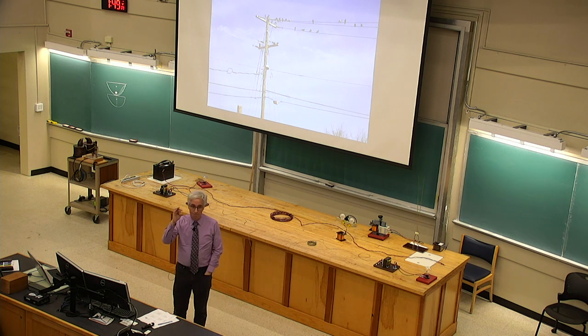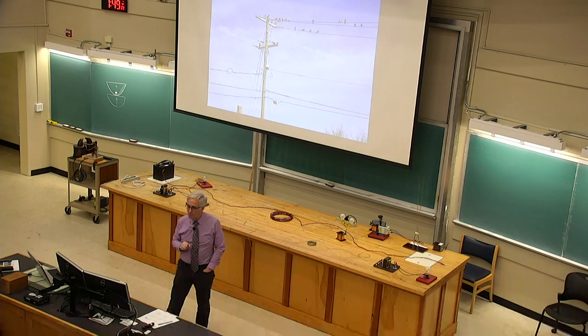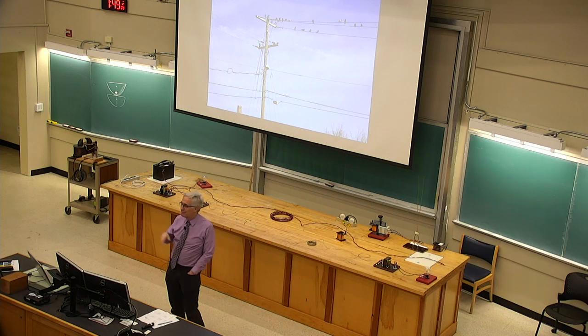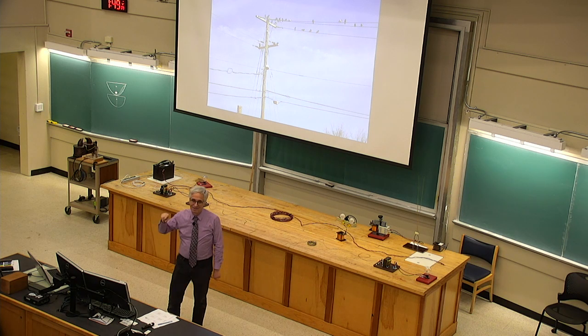The round opening truly is ground, and it should have the voltage of the earth. So 2 of those, basically 2 of the things you can connect to are within tiny voltage of 0. It's the last one, the short slot, that provides the electric power. It's alternately called load, hot, power. That wire does a weird thing.